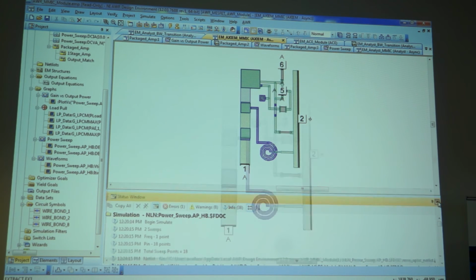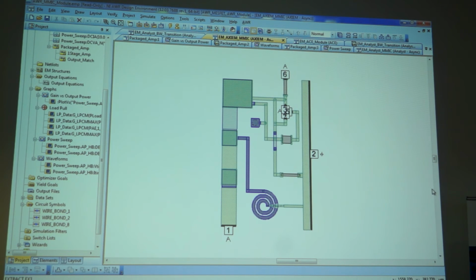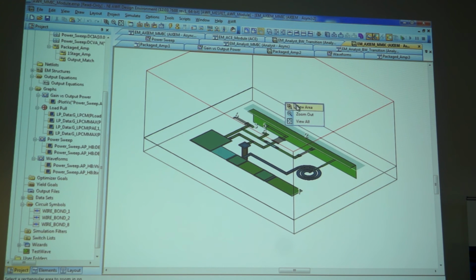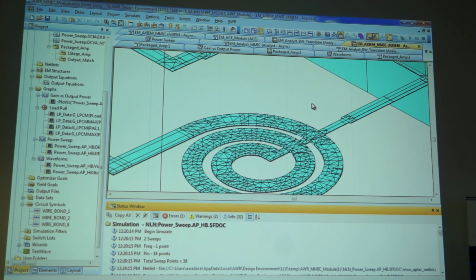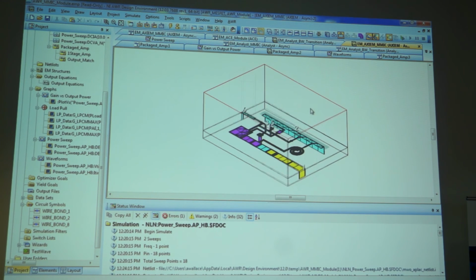That's the one I needed, but slightly small on the screen, sorry. That's the surface of our chip design with a spiral. We send that out to a planar tool. So in 3D you can see two things. We actually simulate the thickness of the metal, and we simulate that with now a planar solver, so triangular mesh. And it's done across all of the interconnect on that design.